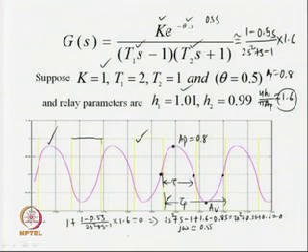Thus, I see that the frequency of oscillations is roughly of the magnitude ω = 0.55. That will give us a time period τp of approximately 2π/0.55 = 11.5. So, if I measure τp, it will be approximately 11.5. This ensures that we are able to obtain a stable limit cycle output in spite of having an unstable pole for the unstable system.